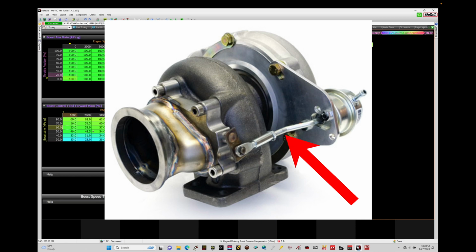When the swing arm is closed, we'll generate the maximum amount of pressure through the turbine housing and therefore across the turbine wheel, building as much boost as we can. If that actuator opens up, depending on where the travel is, whether it has full swing open or somewhere halfway, it's going to have a different amount of exhaust mass flow that's going to bypass across the turbine housing and the turbine wheel. So we'll find the spring pressure inside that wastegate diaphragm assembly will have a certain pressure that it's going to be fully open at. That could be at 10 pounds, it could be at 20 pounds. That's our base spring pressure, and it will actuate and open up that flapper valve at that rated pressure. So it's a very simple mechanical system.